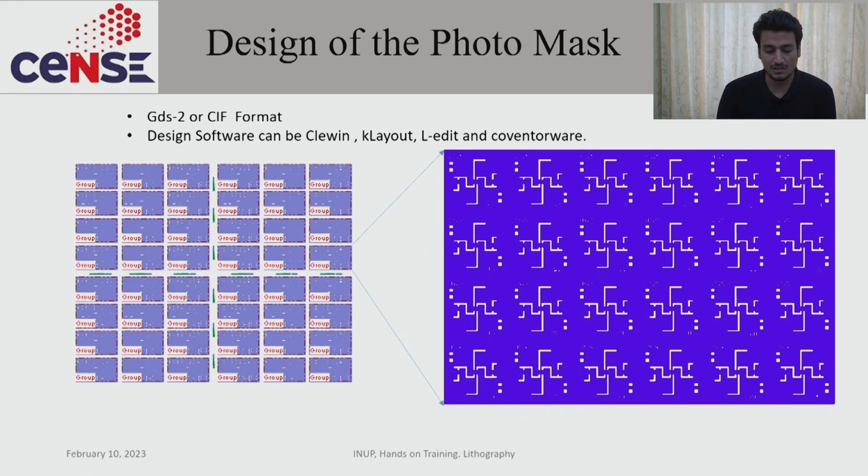So just for example, this is a photo mask design. Whatever designs you are making, we are generally accepting GDS2 and CIF format, because in the Heidelberg tool we are mostly working with GDS2 and CIF files, because we are able to convert only these two file types majorly. So in case you are submitting any design, we suggest you send the design in GDS2 or .cif format.